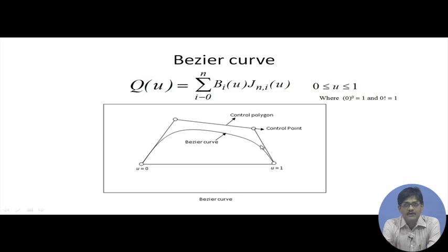So, the points which are making up this control point network, the first control point and the curve, they are coincident. The last control point and curve, they are also coincident. In between, the curve might or might not pass through these control points, and the curve can have different shapes in between, but it is always affected by the locations of these control points.